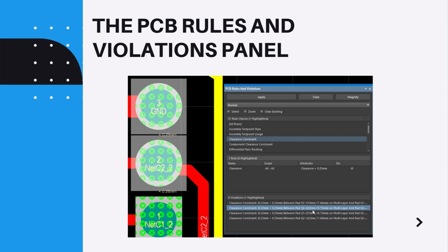The Violations submenu. The right-click violation submenu was described earlier in the existing design rule violation section. Now, this image shows how the violation submenu details the measured conditions against the value specified by the rule. Right-click on a violation to examine what rule is being violated and the violation conditions.